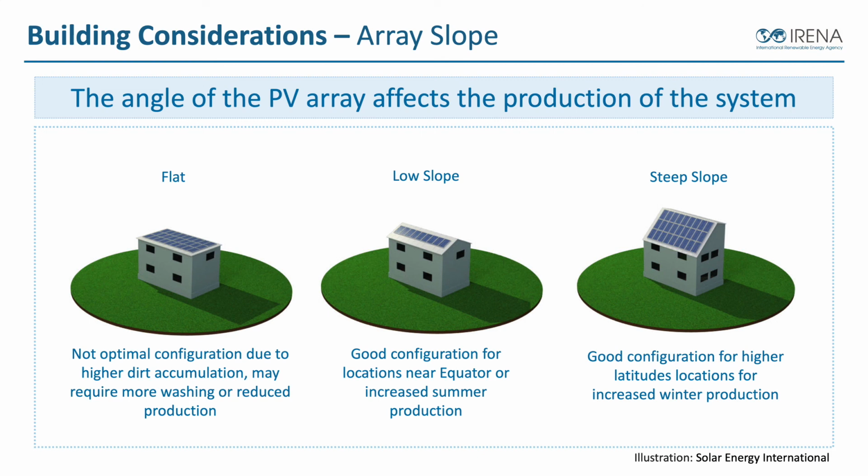But what we find, if it's truly flat and doesn't have any amount of tilt on it, is that dirt and dust will accumulate on that glass surface, and then it will move to the edges and the corners slowly, maybe, and kind of pool over time, but not really blow off or rinse off very well when it rains. And so flat arrays just tend to be dirtier and either have a bigger power impact or require a lot more washing and maintenance to keep that flat array producing what it's supposed to.